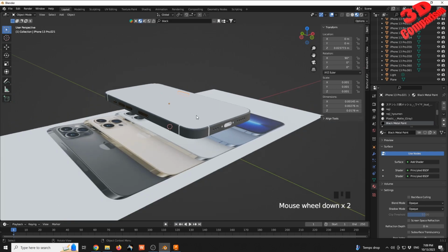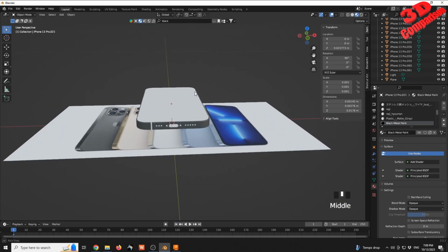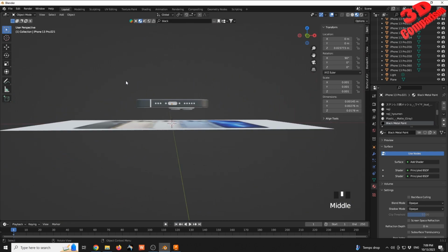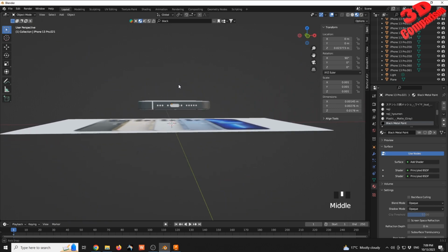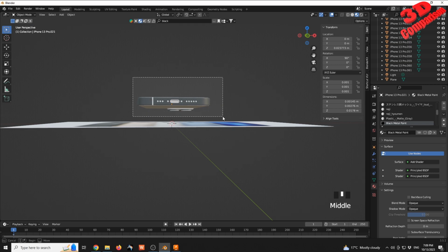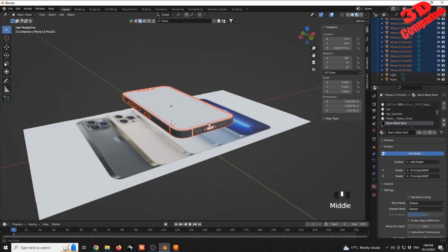Now I will want to select everything over here and make a collection. So to do that, you have to rotate around the model and do a selection like this with a rectangle selection. If for some reason you don't have the rectangle selection, if you press W, this will cycle within all the available selections, but the most convenient is the rectangle selection.